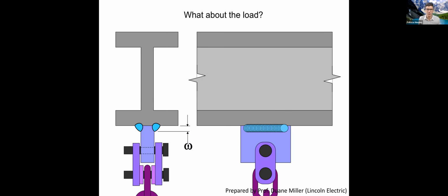Of course, for practical reasons, we're never going to make a weld that is 1/4 of a millimeter, because such a thing cannot be made in practice. But in that case, people define the minimum size you can make a weld. Other than that, when we design a weld, we're going to design it to bear a given load. Of course, if we don't know what the load is, we have to guess what the load would be. But it's not true that we would always design according to the thickness of the members, because sometimes the members might have a big thickness for reasons that have nothing to do with bearing a load.